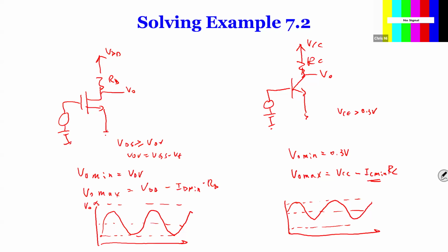Here is the same thing. Here, you're hitting the maximum, but you don't hit the minimum. So your voltage swing is this much, not the range. So the range could be 5 volts, but your swing is 4 volts. You guys understand? So your output voltage swing is different from the absolute range.